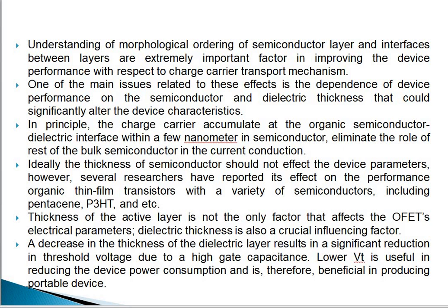When you simulate an organic field effect transistor, ordering of semiconductor layers is very important because it can improve the device performance in terms of charge carrier transport mechanism. One of the main issues related to these effects is the dependence of the device performance on the semiconductor and dielectric thickness that could significantly alter the device characteristics.